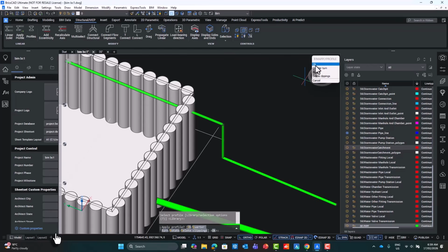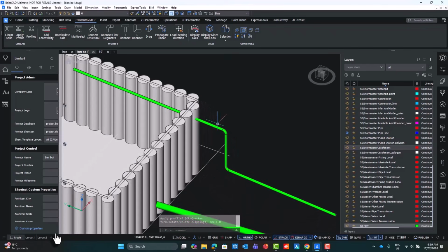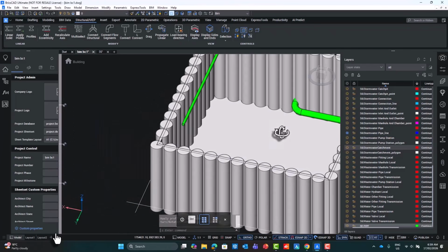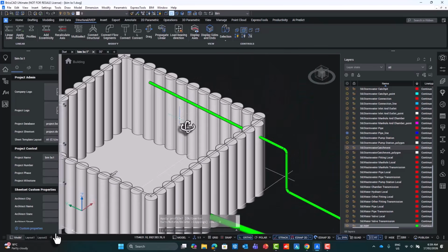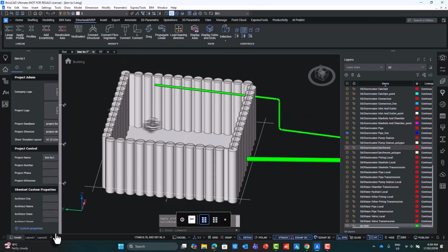Now you can make adjustments and quarter turn and rotate it, but if it's set up fine, it will automatically do that L connect, that junction of that pipe very easily. So once you're working with CAD line work in 2D or 3D, you can start to leverage these BIM tools to convert them into information modeling components.